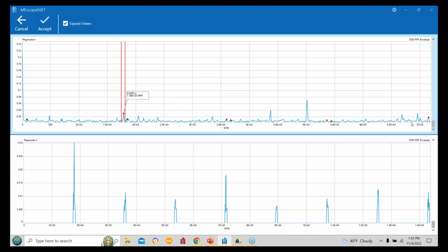And it's barely there. What's left is things that you can go ahead and animate. You can animate the first 4 frequencies here. It's a 4-pole motor, except it cuts off for F max. The order filter expands those orders out to twice whatever your turning speed is. So I get another 4 orders out here that I can animate. And in this case, it would be considered looseness if they had a high enough response.